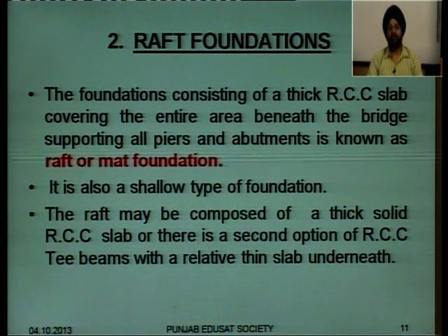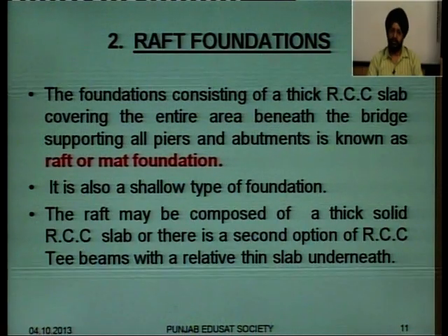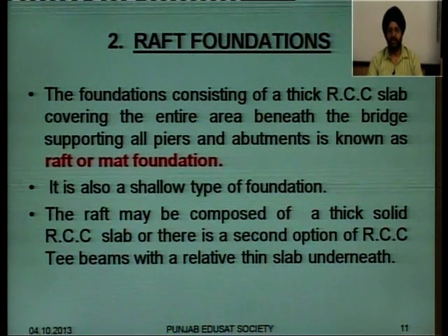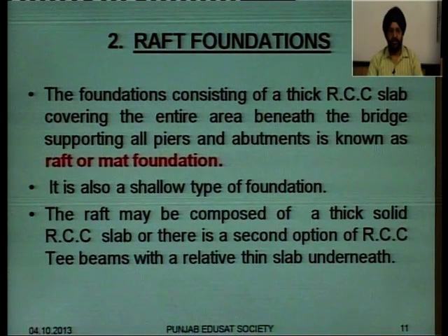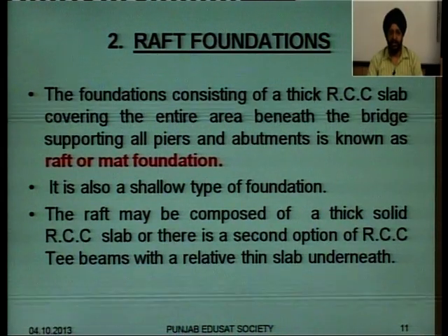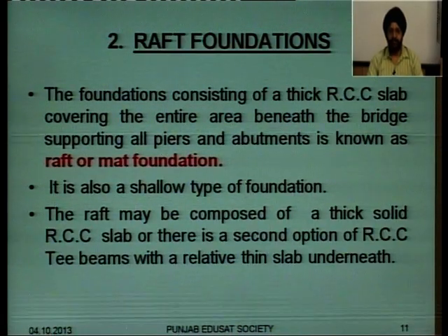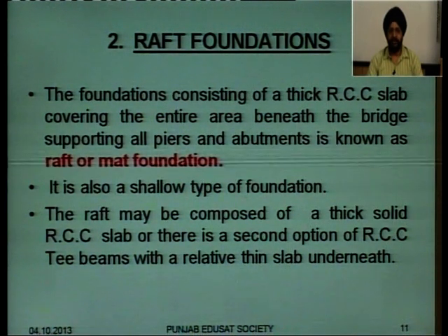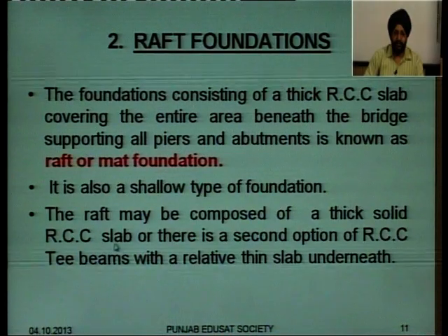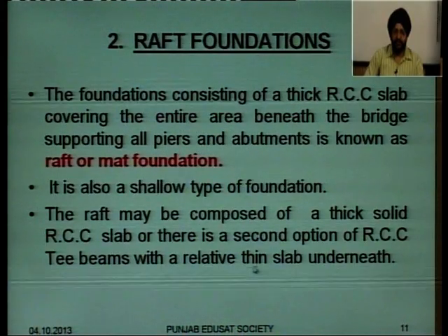Once again, these foundations are also of the shallow type. These are not the deep foundations. So, spread and raft both are considered as the shallow type of foundations, and the raft may be composed of a thick solid RCC slab, or there is a second option of RCC T-beams with the relatively thin slab. So, we have two options for the raft: one, a thick solid RCC slab, or the second option of RCC T-beams with the relatively thin slab.